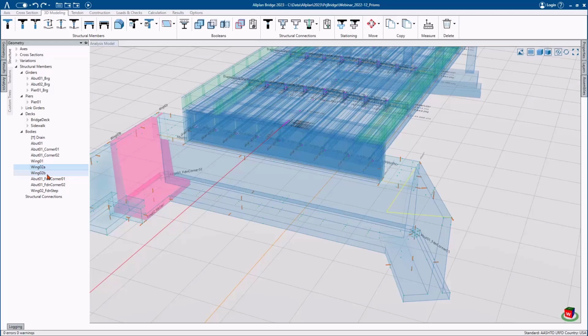In the end, all of these blocks are then unioned together to form one cohesive object within my project, and it is this object that I can add some attribute information to, and it's this object which will be brought into ALLPLAN engineering as a single cohesive structural member. This way, all of those tricky little interfaces are resolved immediately simply by unioning the different blocks together.